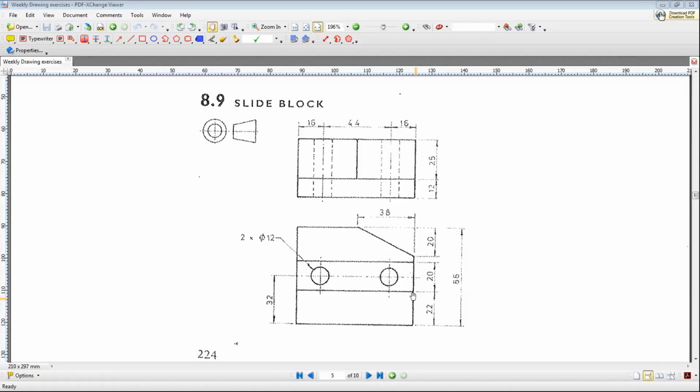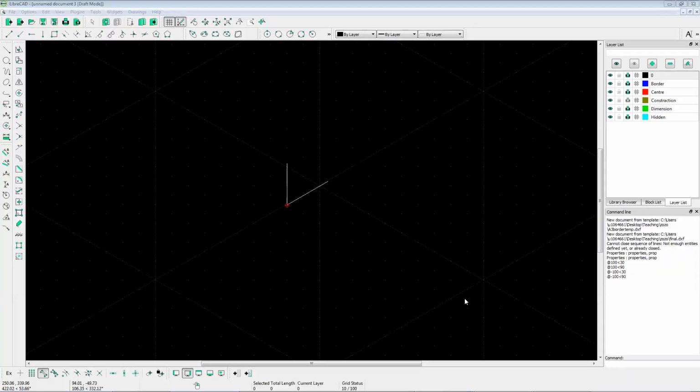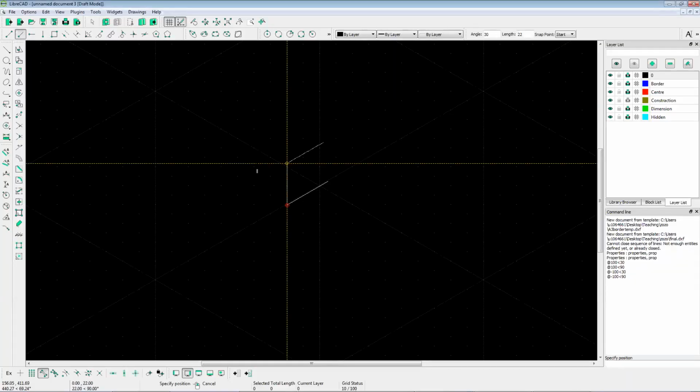So this is the 22, and then we should imagine there is a surface coming to the front here that contains these surfaces, these circles, because if you look from the top view, these surfaces, these holes, look like hidden details here. So that means there is an extra bit from that surface coming in this direction. So it's coming in this direction by 12, so I'll go by 12 there. In this stage we needed to go in this direction.